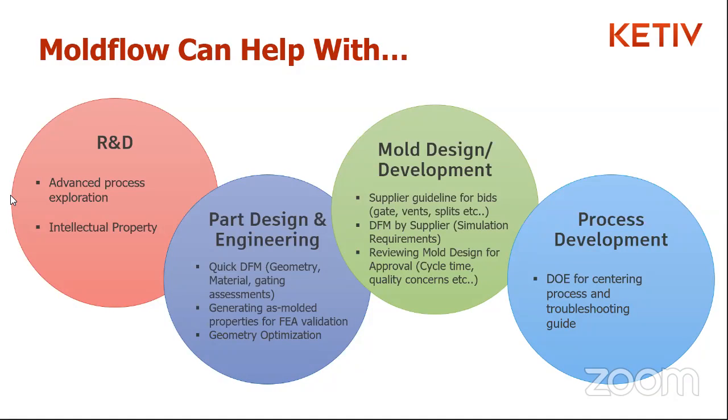So what are the different parameters that are going to affect your process, right? Whether it's the injection pressure, the mold temperature, the melt temperature, whatever that may be, this process development portion of it through Moldflow will help you understand which variable affects the entire process the most, and then you can kind of zero in on that and try to modify that to really understand what that sweet spot is.